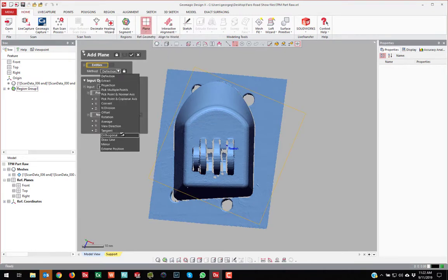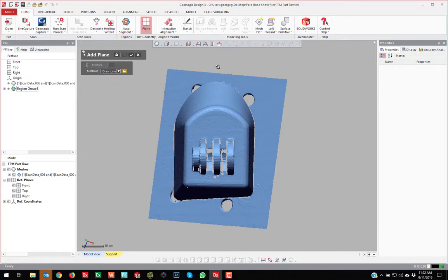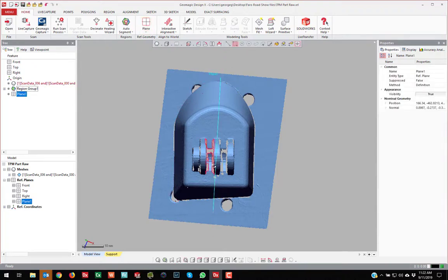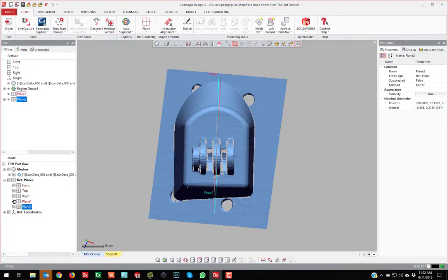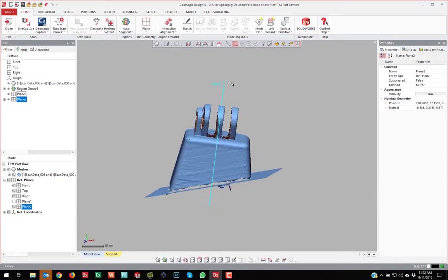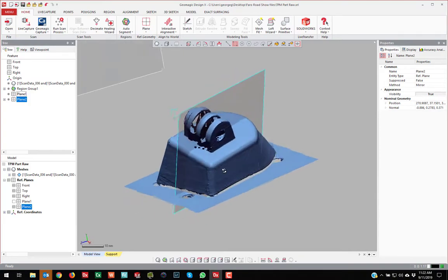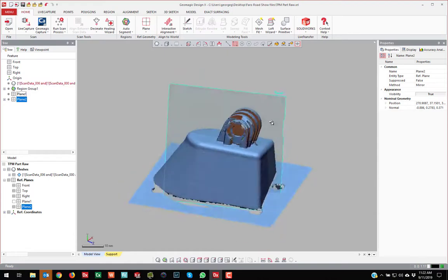And we can actually extract a mirror plane, or a symmetry plane. But in order to do that, you have to give it a good starting point. So I draw a general plane of where that plane ideally should be, then select both the mesh and that plane and tell it to generate a mirror plane, and hit calculate. The software will actually calculate the most ideal mirror plane down the middle there. That's really interesting how you're able to calculate that.